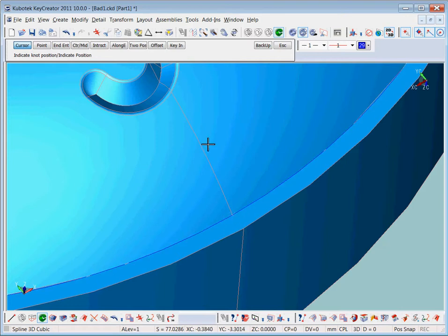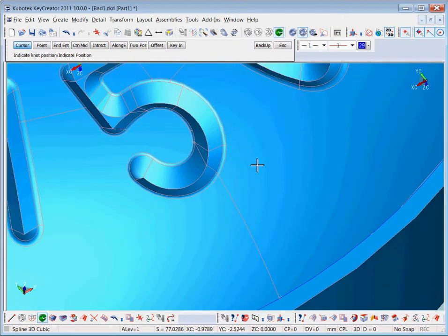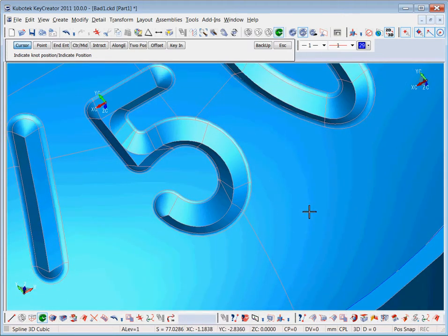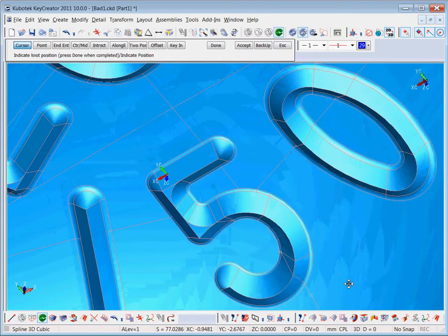So I'm going to the end. Now I could go to this end, but we've already got some curves. We want to pick them exactly on the curve, don't we? So if I hold the Shift key down, there's a near option, and I can just click, click, click, click, right? And I can just follow any of the curves that happen to be on the centre.